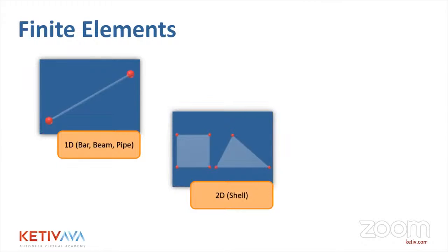2D elements are typically surface elements with triangle or quadrilateral shapes as their basic shapes. These surface elements can have either regular shapes or irregular shapes in the model itself. And they're often used for 2D elasticity problems, since they account for plane stresses and plane strains. Now, the fundamental property of a shell element is the actual thickness. You can assign this thickness property to geometric surfaces or geometric solids, depending on what your model requires.